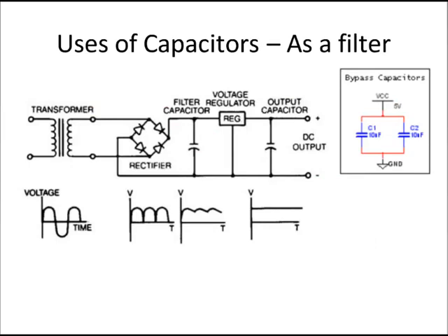When we were creating a simple circuit in Multisim, we saw some bypass capacitors up in the upper right-hand corner of the schematic capture. And their purpose was to filter any ripples in the DC voltage in the circuit to ground. And here's an example of the capacitor as a filter. What I have here is a power supply that converts the AC voltage coming out of the wall into a DC voltage that we would use, say for example, in our computer.